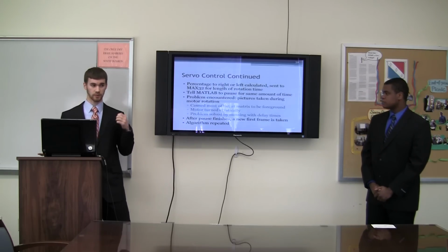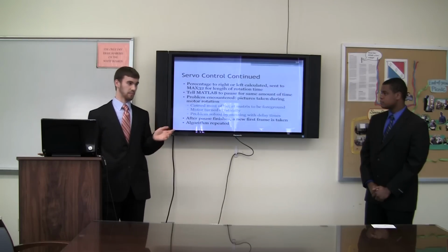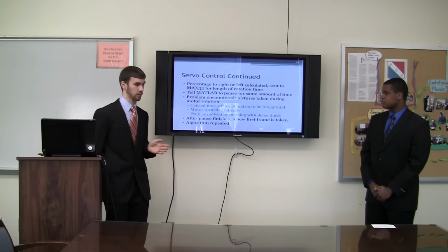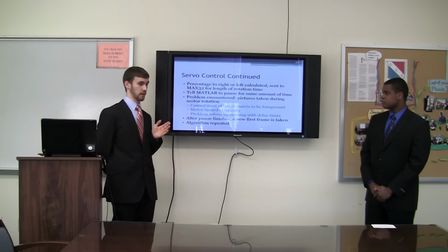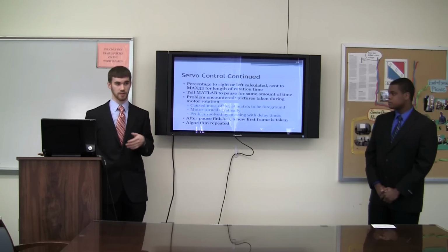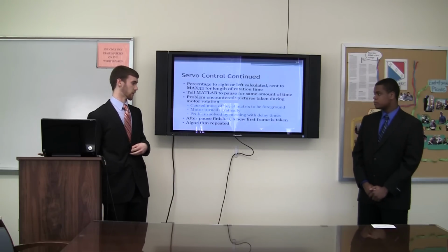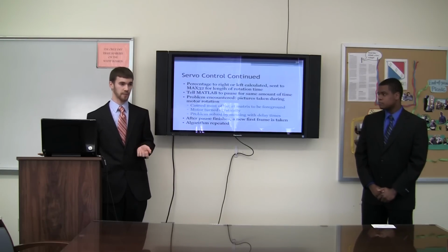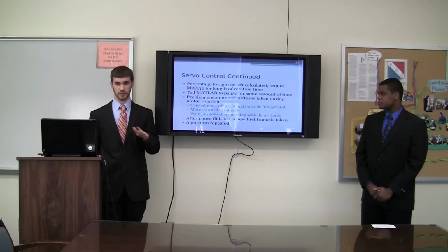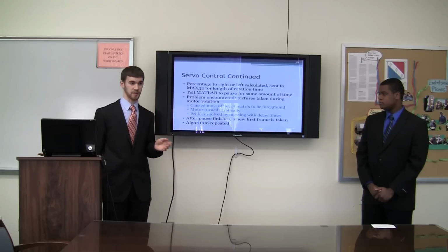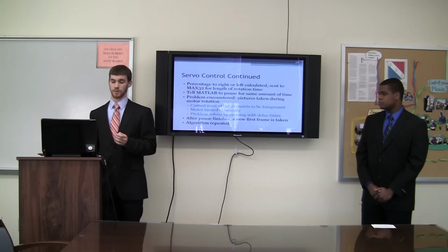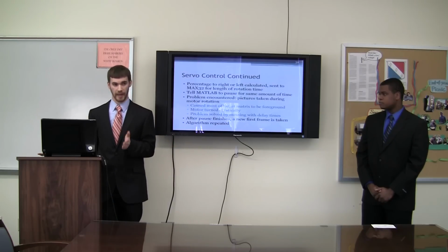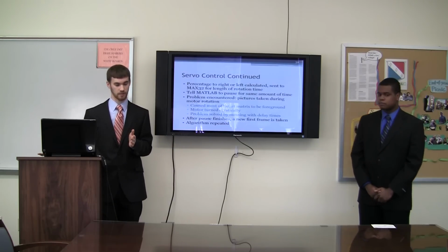Otherwise, we encountered a problem where the camera was taking pictures during motor rotation. If we don't tell MATLAB to stop during motor rotation, it's going to take one picture, then another picture, subtract them, and do the entire frame difference algorithm. That resulted in a majority of the targeting matrix having foreground pixels, meaning something was moving. But this wasn't true. It was only seen as moving because the camera was moving while pictures were being taken. So we need to do the algorithm, turn, wait for MATLAB to stop, then start taking pictures again.